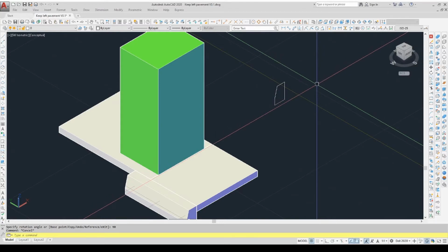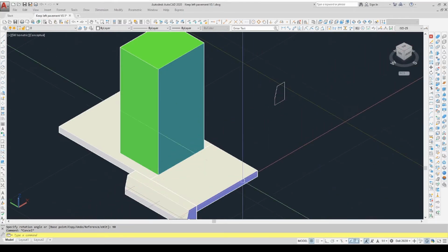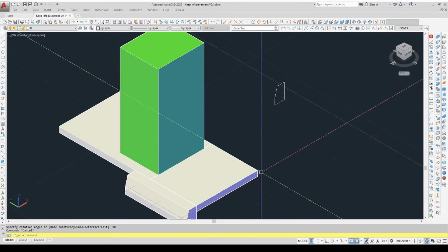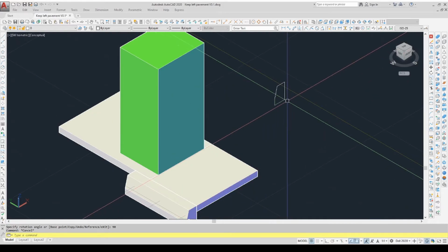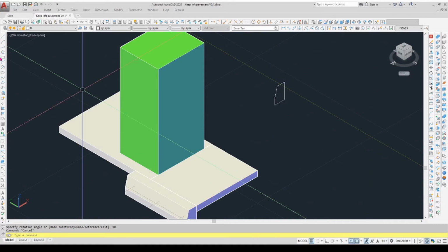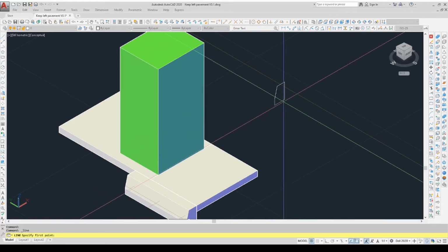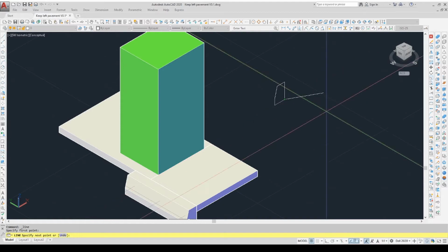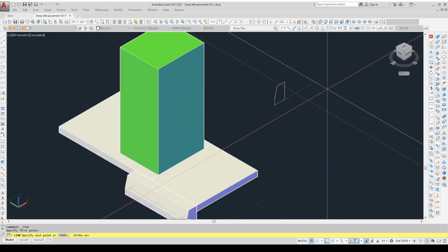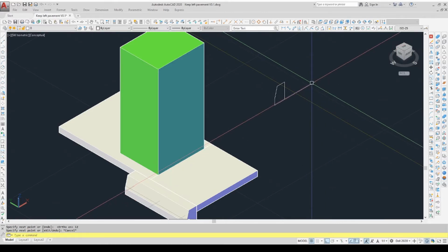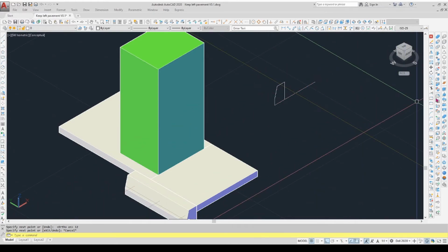I'm going to revolve it around somewhere around here. Now I want it to be a curve around the front, so that's 24 inches. The center point would be 12 inches away, so I just need something to lock onto when I come to revolve this. So I'm going to draw a line very easily, just as a reference point and nothing else, but delete it later, put my orthogonal on, and define a line that is 12 inches long. So now I've got a point that I can revolve it around.